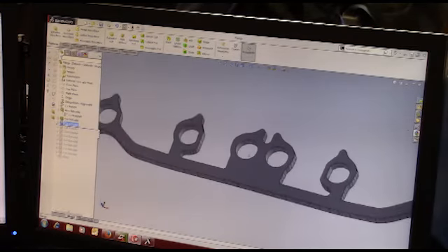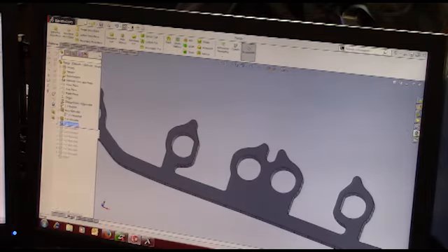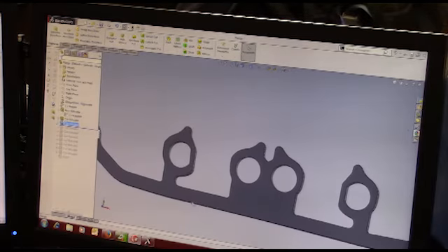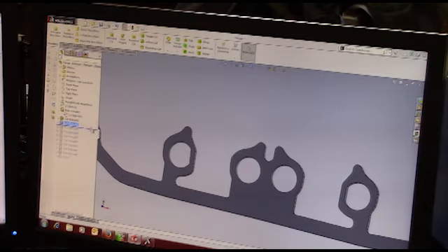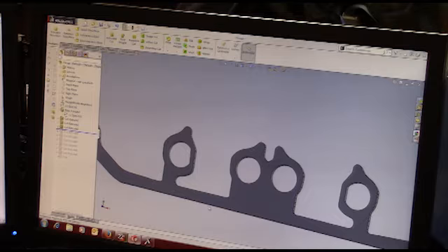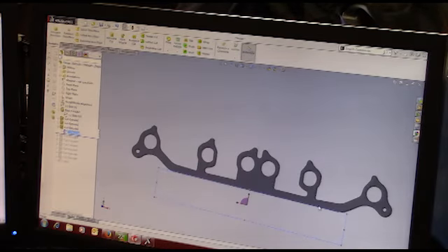On the bottom here, on the original part, there's this little curvature which kind of waves along the bottom. For us, once we machine this part, we have to flip it over and we have to have some true features to hold on to. So I took and made a cut on the bottom side of that part, basically this cut right here, to give me a real true straight surface to start working with on the bottom. It doesn't affect the function of the part, it just gives me a good feature to work with.